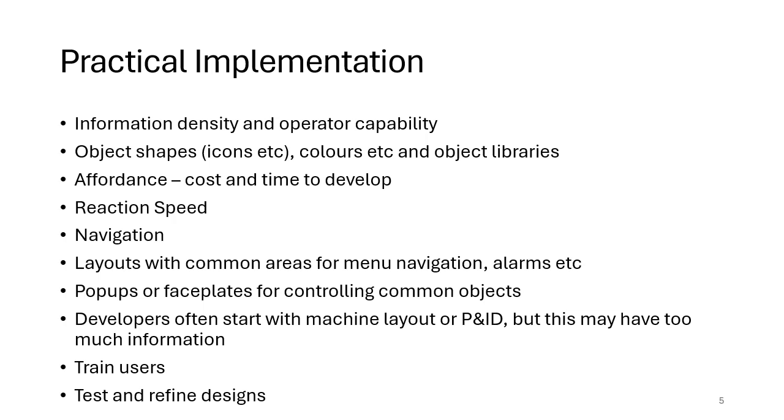That will cause a pop-up or a faceplate to appear, which could give the operator a lot more information that they need to actually perform control. So, for example, they might want to put it in auto manual mode, they might want local remote, there may be the set point capability, there may be alarm acknowledgement, that may even link through to trending. So depending on what the application needs, those pop-ups and faceplates can be a time saver because you only need to develop them once for each type of object, but they're also a great way for the operator to drill down and get more information and more context about what they're controlling.